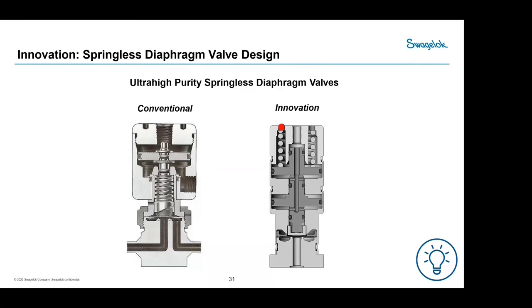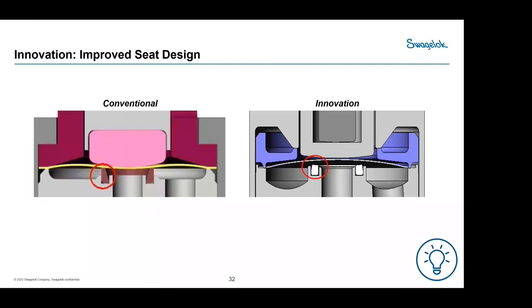And what's changed? The conventional valve had a seat designed for optimal shutoff performance, with different angles, different thermal expansion, different media, different material. And then when we are innovating, we're looking at all those factors. We're looking at the chemical attacks, the thermal variations, the swelling, and all those factors. The teams are working on trying to make sure we pick the best material for the application. So we have to continue to improve the seat design, the seats, all the valve aspects.